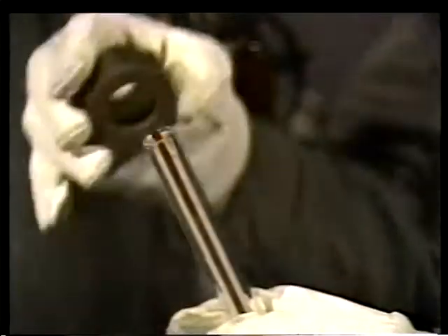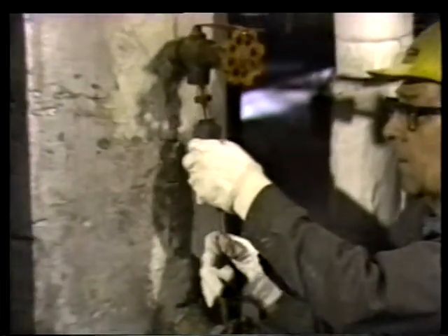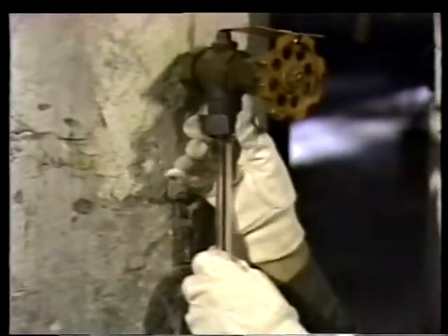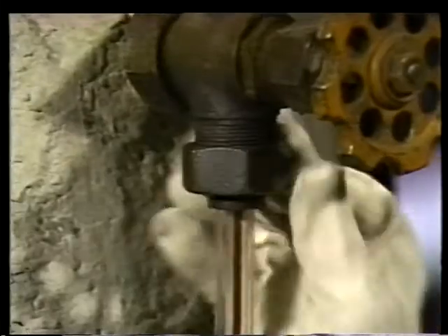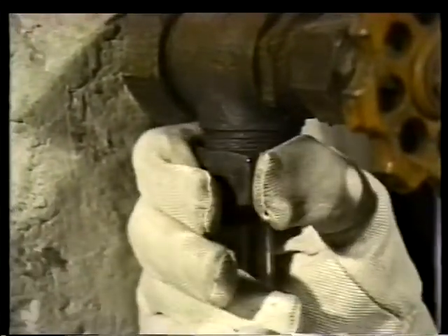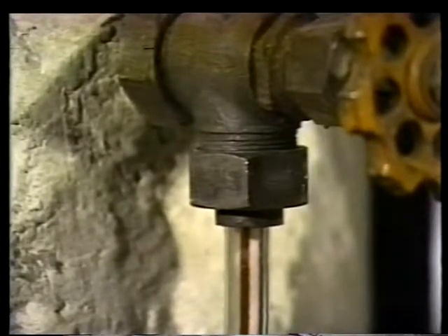To install the glass, slip the nuts, glands, and a set of seals over each end of the glass. Place the glass in the gauge valves and tighten the nuts until they are snug. The nuts should be tight enough to prevent leakage, but not tight enough to prevent expansion during temperature increases. Now be careful not to bend or twist the glass when you tighten the nuts, or the glass will break.